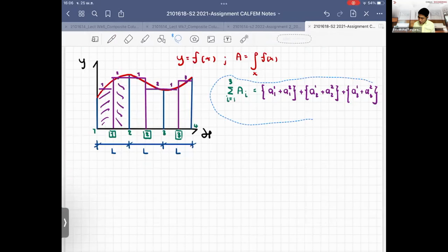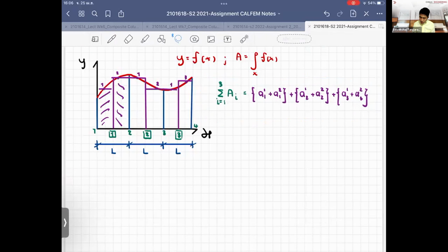By having this type of approximation to get the area underneath the curve, to get it more accurate, you have 2 options. One, put in more Gauss points to approximate the curve, or the other, you discretize the structure more. The more you subdivide the portions, from 3 to 6, 6 to 12, to 24, you start to get the value closer to what is actually required here, which is the real solution.